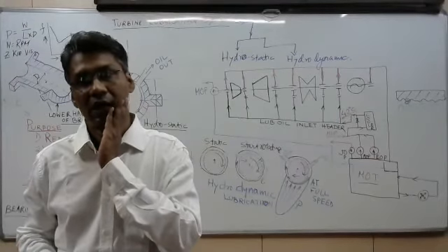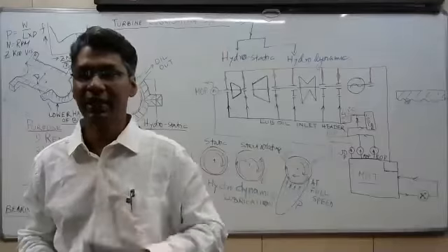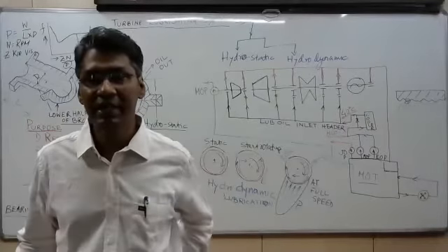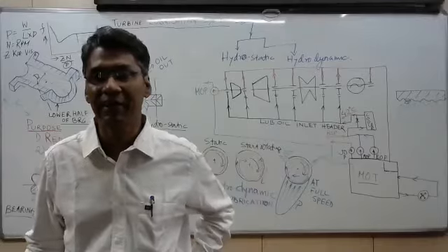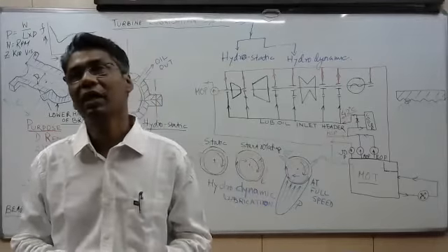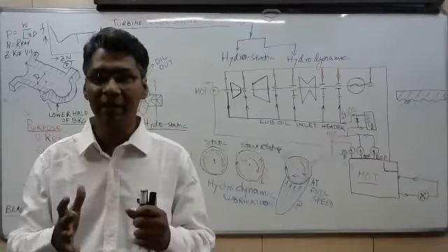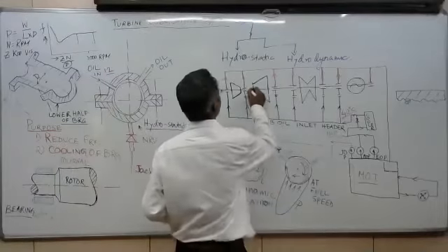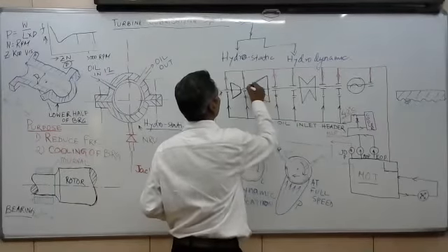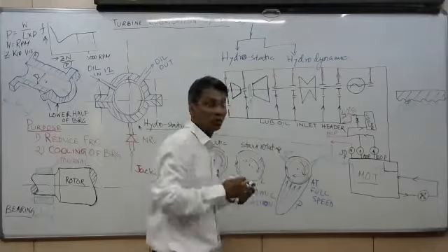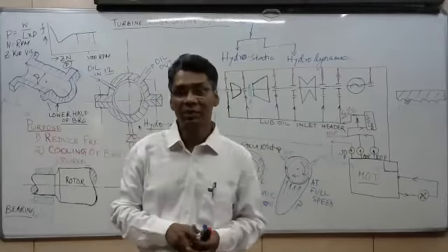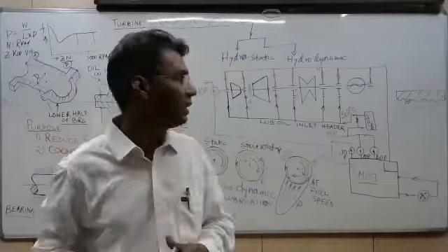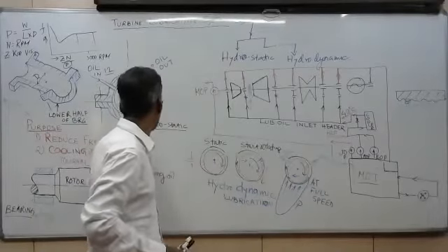So Arindam Banerjee has raised a question: where is the duplex filter situated, and is there any thrust bearing filter? Yes, because the thrust bearing pad is a load carrying bearing. Mainly the thrust bearing is provided over here, right? So we provide a special oil filter. So duplex, and for the journal bearing, this bearing,